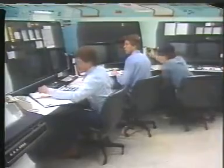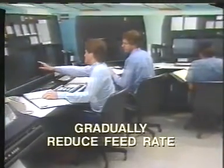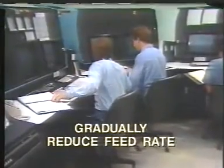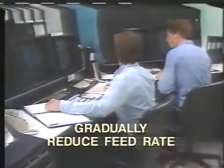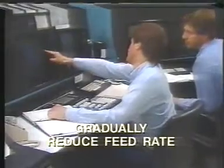The first step in most planned shutdown operations is to gradually reduce the feed rate into the column. As we reduce the amount of material put in the tower, the product output also decreases. By making gradual feed rate changes, the tower instrumentation can maintain the design conditions inside the column.